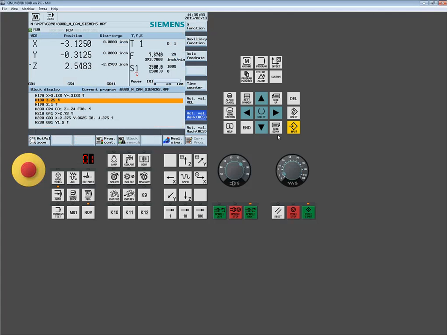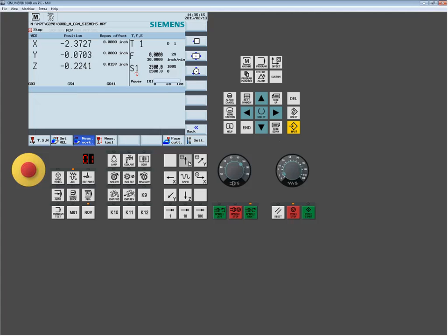Now, a couple of the other modifications I did in turning this into a subprogram: I commented out, I could have deleted, certainly, all tool change commands because I want to do that up in the main. I don't want to have nested tool changes. I commented out any kind of advanced technology cycles, corner rounding, feed forward functionality, anything like that. I don't want it here. I want pure cutter path.